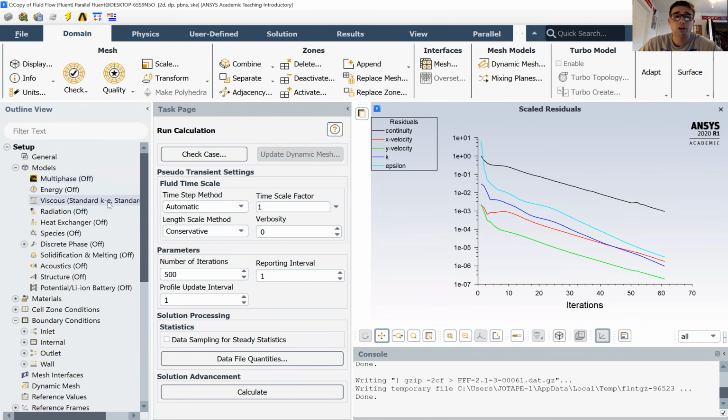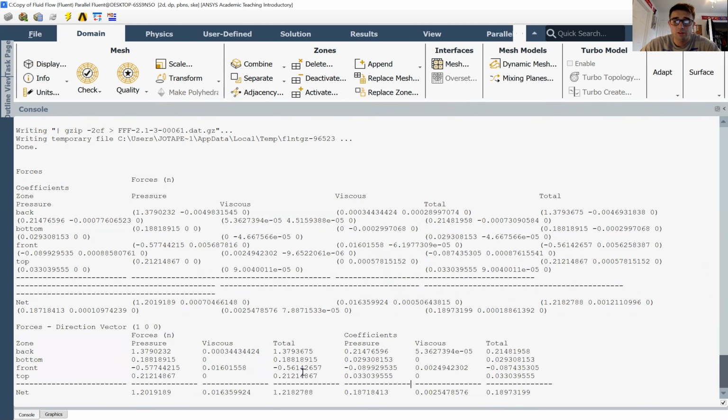And as you can see here, this entire area, this bottom part, is the forces that are found, the drag forces and drag coefficients that are found on the semicircle. So you have your pressure force, you have your skin friction force, and then your pressure coefficient and viscous coefficient. And the totals, so this will be your total drag coefficient, and this will be your total drag force. And again, it's important to note that this is in the x direction vector. So once you have this completed, you can then move on to the contouring portion of this, which can be done in the results section, making sure that this is only done after you complete the calculation, because this will not work if you don't have that done.